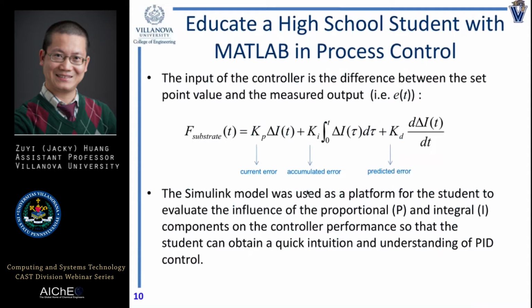But I introduced the physical meaning of each term in the PID controller, and then I showed the student how to build a PID controller in Simulink. The student can play around with KP, KI and KD so that he understood how PID works and how each term affects the PID controller's performance.